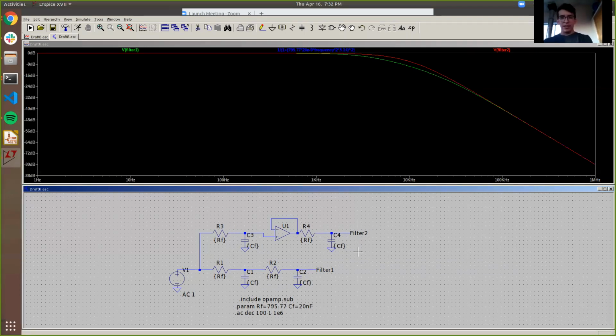You probably noticed that he used a different type of filter, and what he ended up using was an LC filter. The reason for that has to do with the fact that one of the biggest losses in a circuit is when you have a lot of current running through some resistance. That's going to create heat in the real world. So let's say you're designing a buck converter that was outputting 5 amps. You don't want 5 amps running through a resistor to power your load.